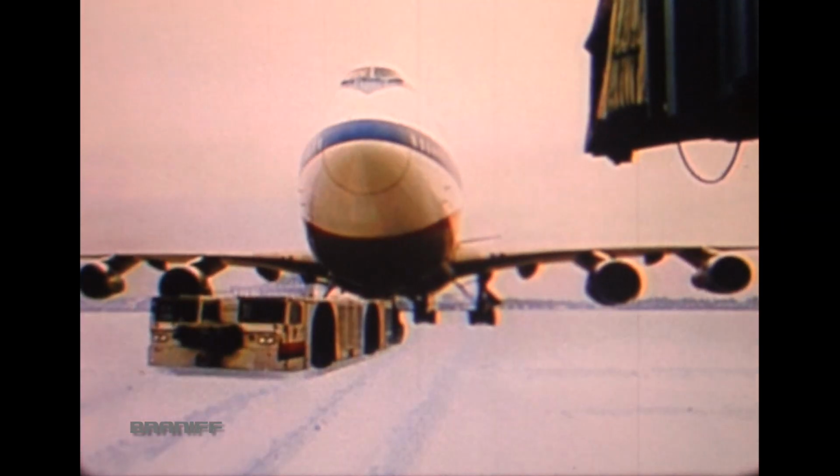Taxi operations during adverse weather conditions require extra crew alertness. Let's discuss some of the areas that should be considered. Avoid lengthy ground operations in icing conditions. Shorten taxi time by remaining at the gate as long as possible. This reduces the time between de-icing and takeoff. When departing the gate, use a pushback instead of thrust reversers.